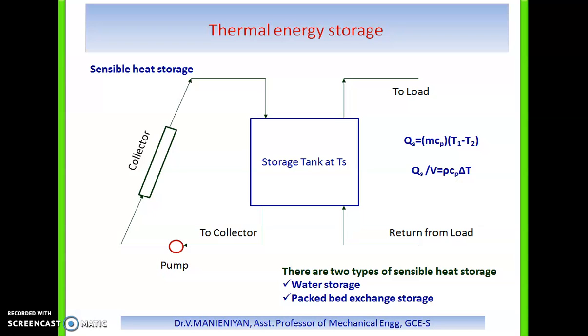If there is no phase change and heat is just absorbed, that is sensible heat. Otherwise, if the material changes phase, that is latent heat storage. It is possible for both sensible and latent heat storage to occur in the same material, when the solid is heated, then melted, and the temperature rises further. Normally, thermal storage is essential for both domestic water and space heating applications. Storage is also required in industrial processes and agriculture systems. So the storage system material depends upon the particular application.